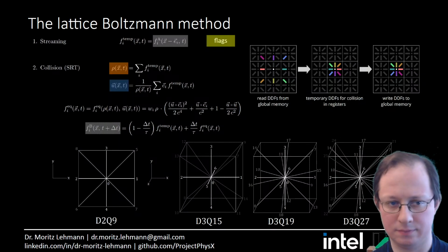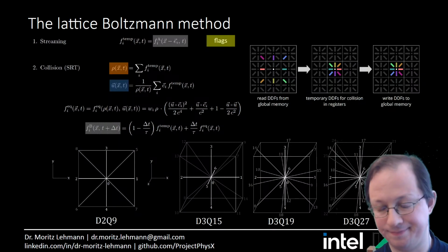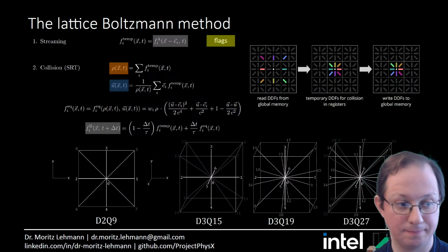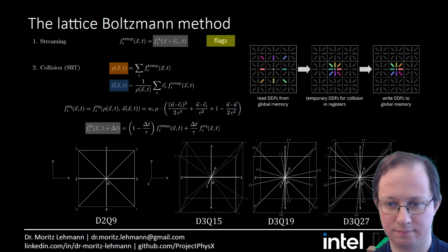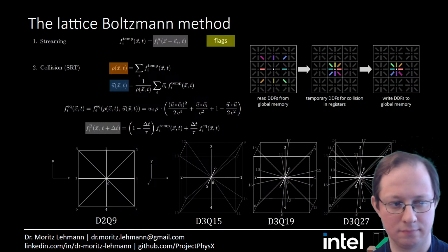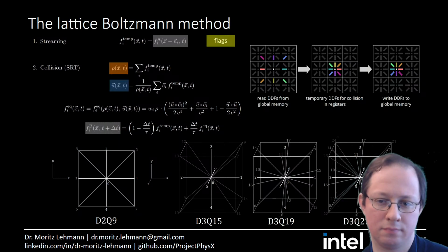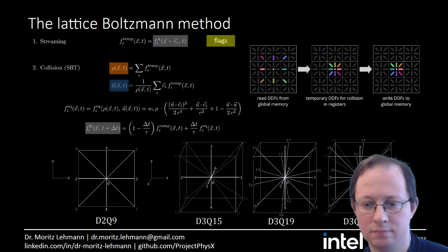So you have some data for every grid cell, and if you want to resolve fluid flow in high detail, in 3D it goes into the billions of grid cells, and the memory footprint just totally blows up. And that was the big thing that I got under control finally in my PhD research, optimizing Lattice Boltzmann for smaller memory footprint.